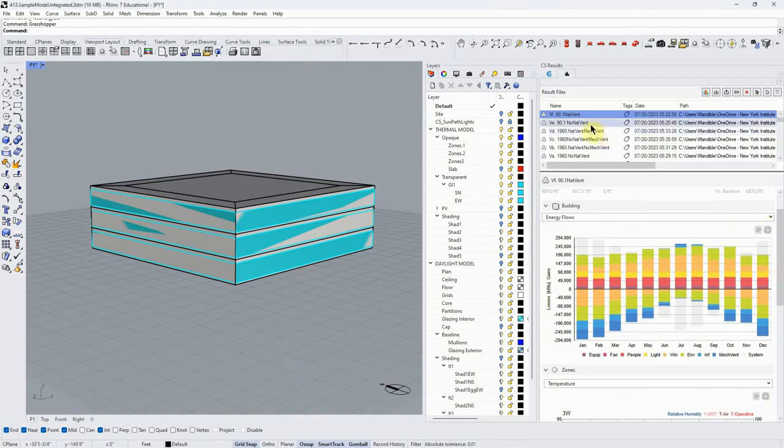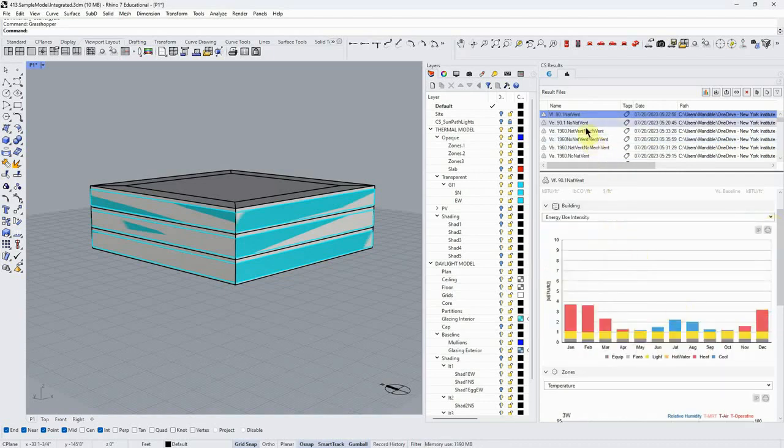And we see that the mechanism is the same. Here we're going to add losses in the summer, and we don't seem to be changing in the winter, which is what we'd want because we're not trying to have the windows open then. I don't know if that's an infiltration issue. I'm not sure, but we're being broader here. And so again, we go from more cooling load to less cooling load with natural ventilation.